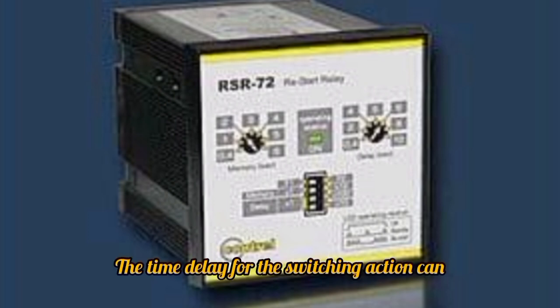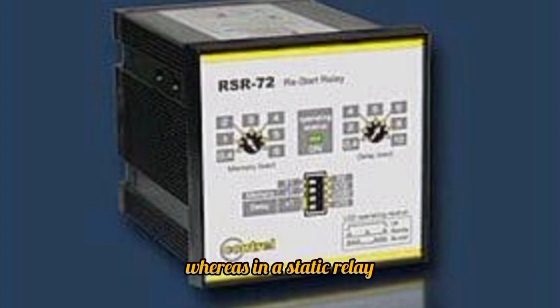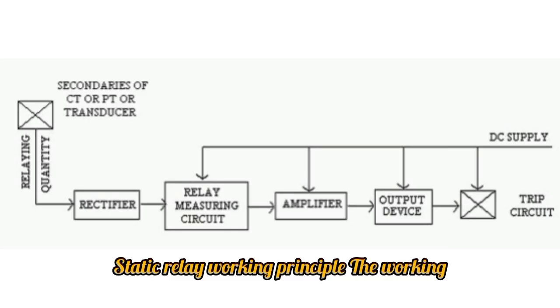The time delay for the switching action can be adjusted by adjusting the distance traveled by the disk, whereas in a static relay the delay can be set by adjusting the value of the resistance in an RC time delay circuit.